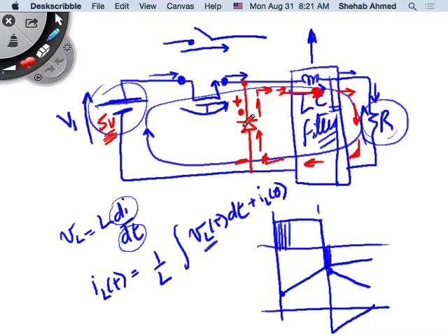For it to block, it has to go through a transitional phase where all the stuff that you studied in 370, where you have a depletion layer, and as soon as you have the proper characteristics for the device to turn on, electrons and holes will flow and all that kind of stuff that I don't care to go through in the class. That depletion layer will have to build up again for the diode to block, right?